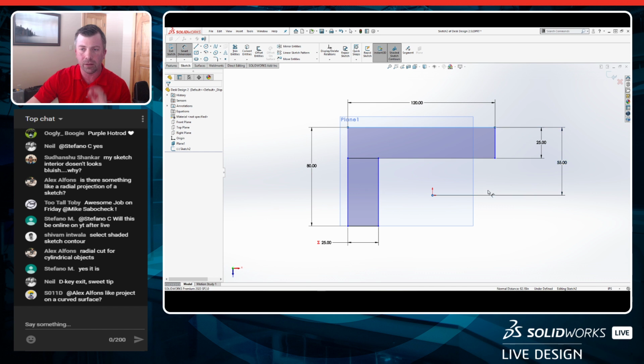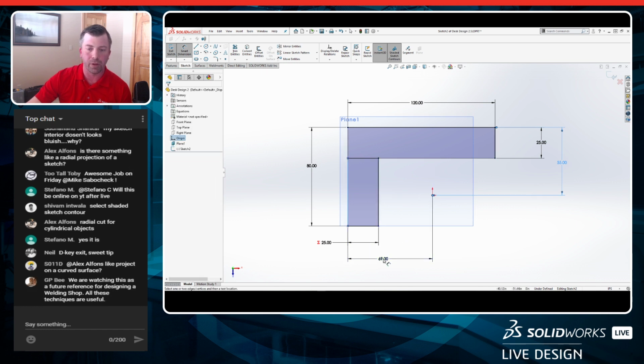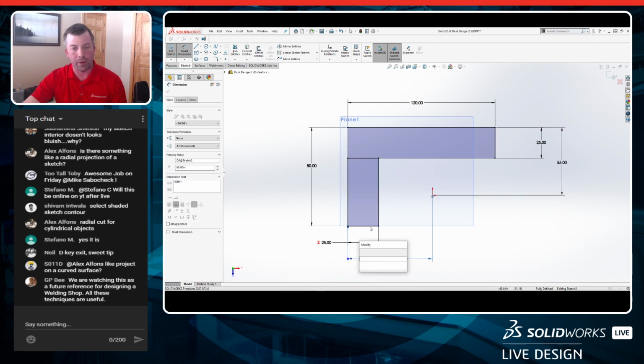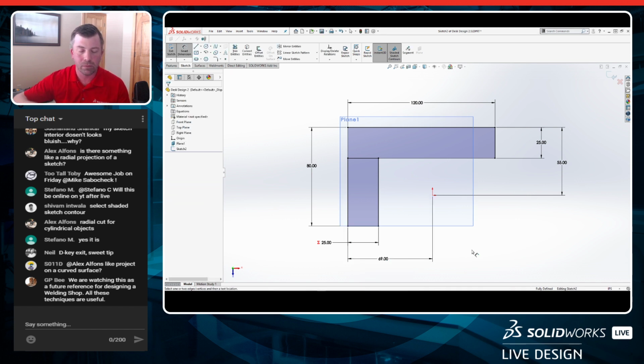So let's set that at a distance to the back wall to the origin. And these don't really matter. It's just making sure this thing doesn't go flying off on me. And we'll do that at 69 inches there. And just like that, we've got my fully defined sketch. I know it because it's all black lines put in here, and we can start to add a few more things.